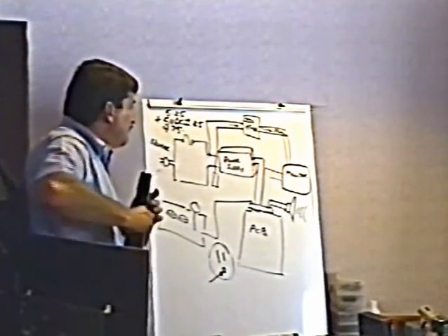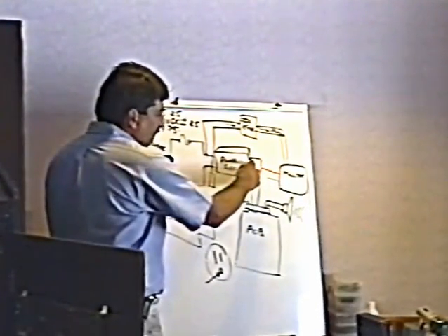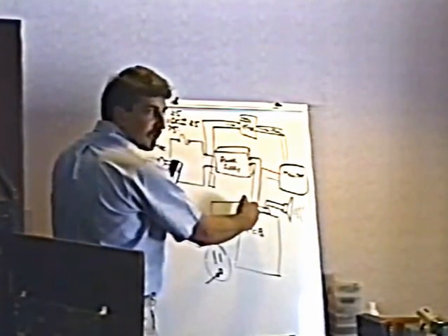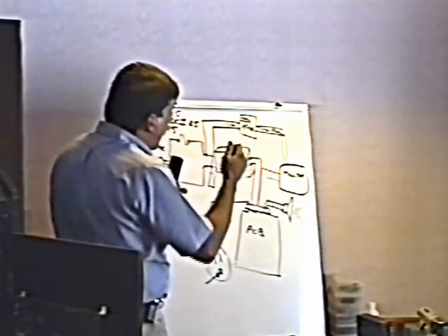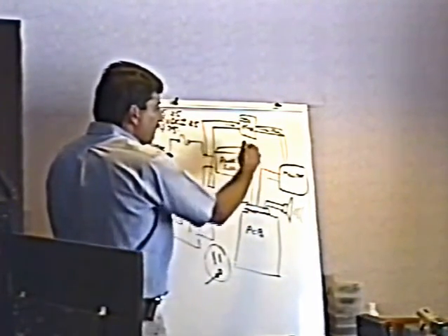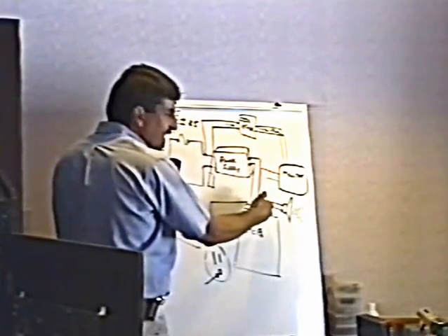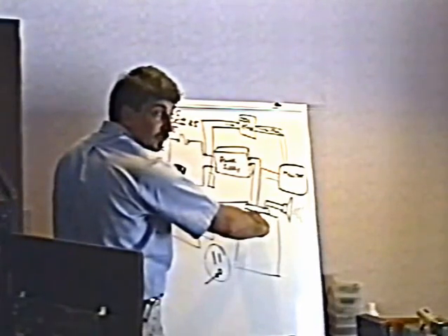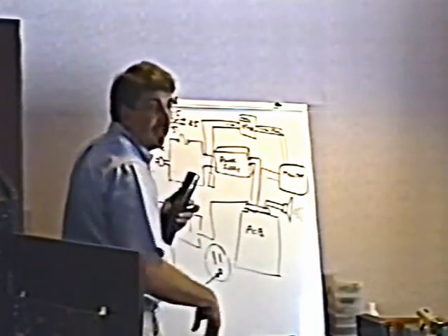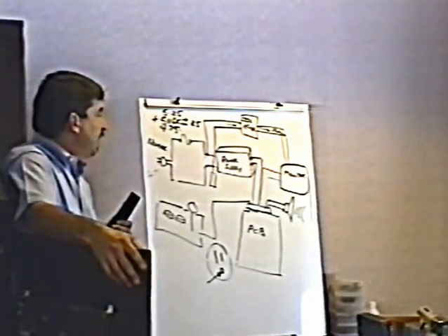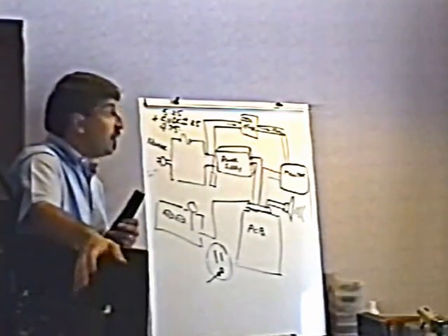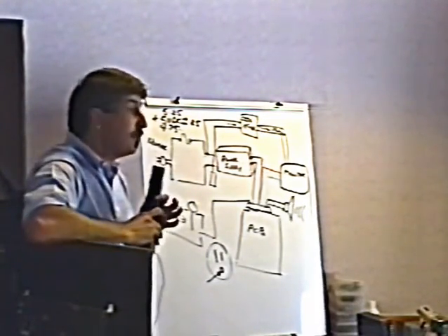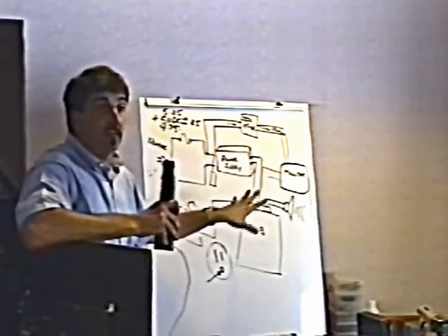You don't want to do that, because if you use this as a ground and just check the 5 volts here at the board, you're not checking this ground connection. In fact, I've screwed myself up that way. I've had a bad ground connection here. Using that as a ground, I checked it here, and I did have my 5 volts. But if I had gone right across from here to here, I would have seen that I didn't have my 5 volts. So you're not checking that whole path that way. So when you're checking the power at the board, you really got to go right to the board. In fact, what I'm going to show you right now is an even better, more universal way to do this. Does this make sense so far, though?